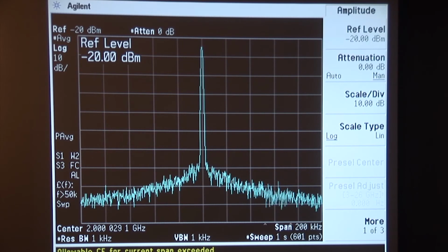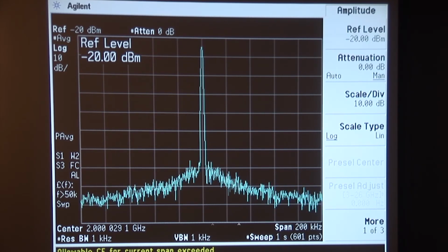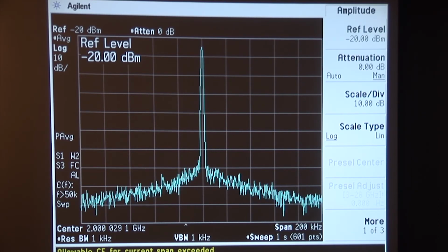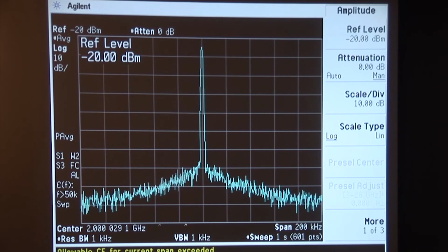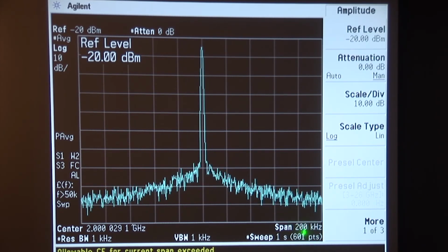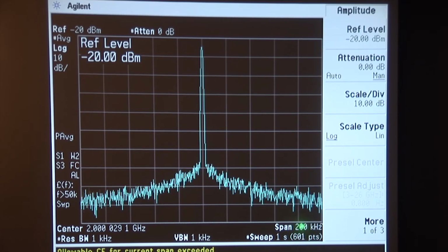It means that as we're spanning across this screen, we're not developing any gaps on the measured spectrum between measurement points. But let me take you to a point where we exactly balance out, or exactly equal, the amount of spectrum that we're convolving with our IF filter with the number of points. Let's suppose that we span a range not of 200 kilohertz, but of 600 kilohertz. So we're just going to change the span here to 600.